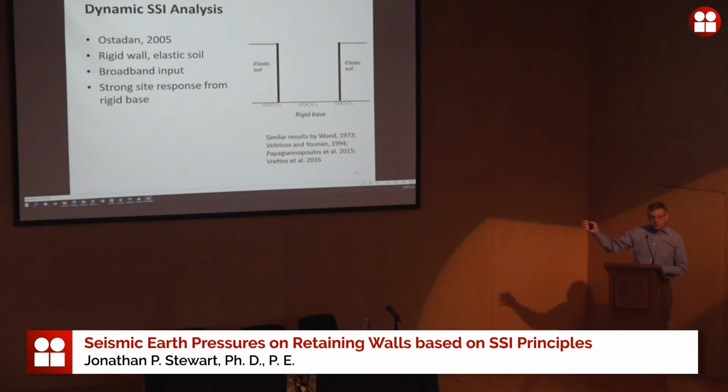This is dynamic analysis. This is essentially direct analysis for a rather simplified set of conditions. You have a rigid base, you have a rigid wall, and then you have elastic soil. Many different investigators have considered this situation. I'm going to look at one set of results from Farhang Özdağ, who's an engineer at Bechtel and has done a lot of work like this for the nuclear industry. So this is the conditions I described.